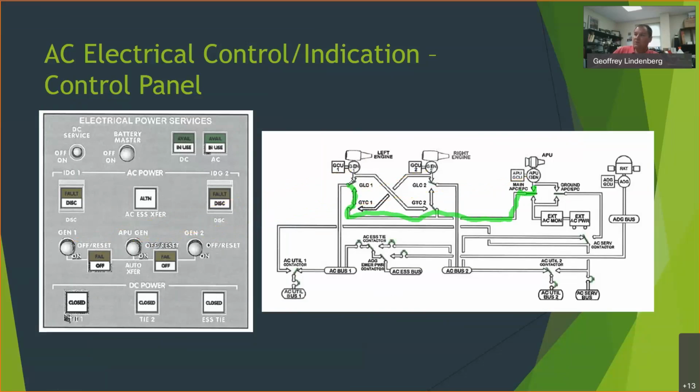It'll go up, and these switches will go this way. And this switch will be this direction. They'll both be down, supplying power to each of our buses. But as soon as we turn on the generator, that's if the APU generator is running, or this is down to the external power source as well. We can have external power coming in and going this way as well. Either one, APU generator or external. It's going to be one or the other. The switch right here will go one way or the other.